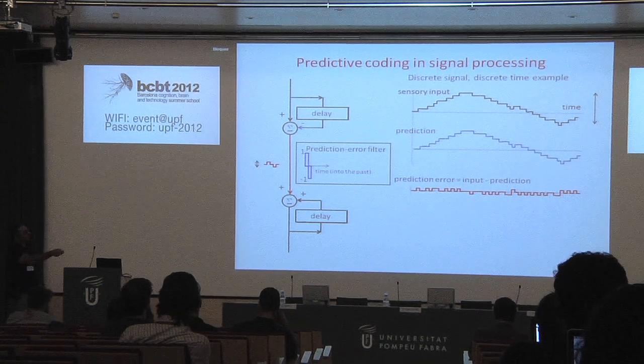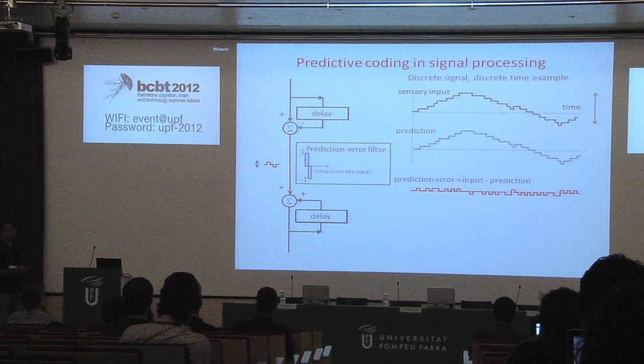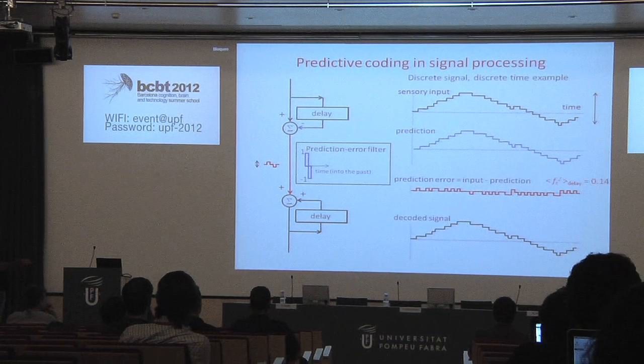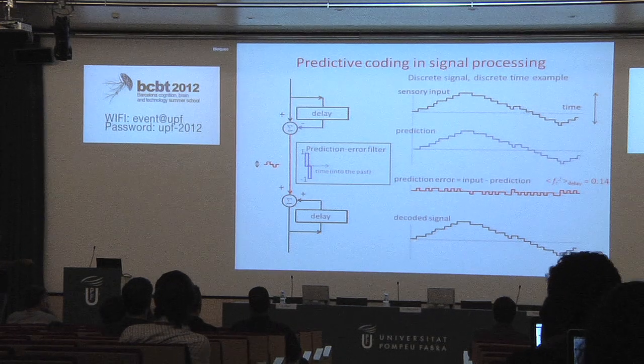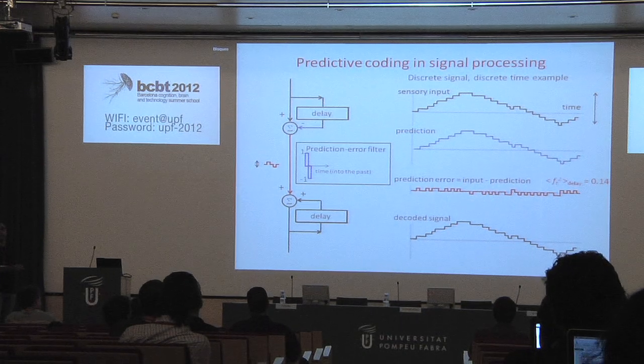So you can look at this filter and you can see that it is kind of a discrete derivative, right? You take the current value of the signal minus the previous value of the signal. So when you want to invert it on the receiving side, the opposite of the derivative is an integration, and that's why you build the circuit which effectively integrates the signal, and you can reconstruct it by putting it through the circuit, and that reconstruction is in fact lossless if you don't have noise in the transmission. So this is indeed a compression scheme that works very well.